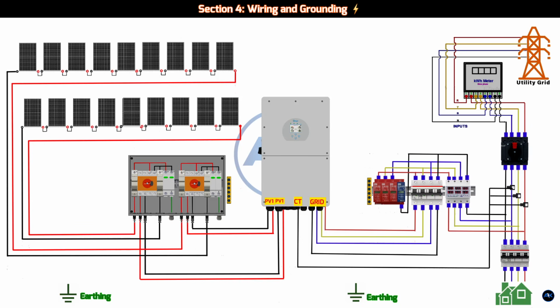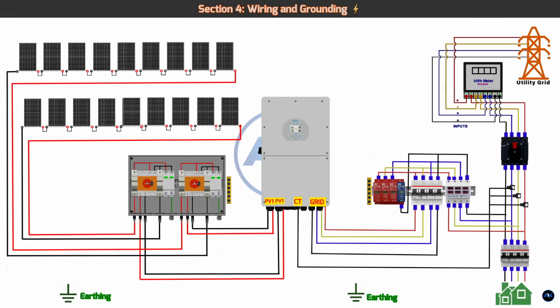5. Final connection. Connect the output of your new 20 amp solar breaker to your main busbar. This final connection allows the power from your inverter to flow into your home's electrical system and, when you produce more than you use, back to the grid.